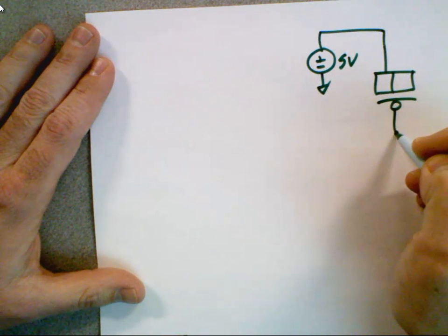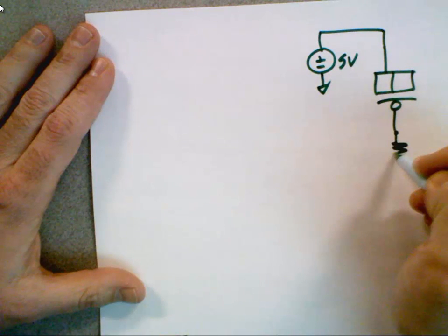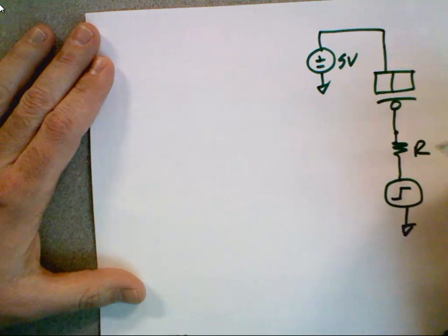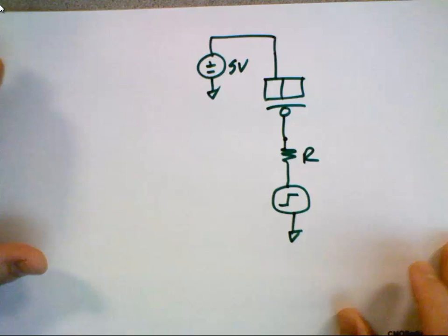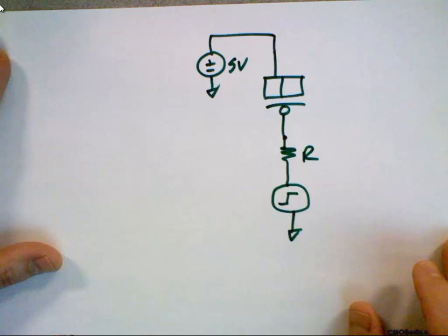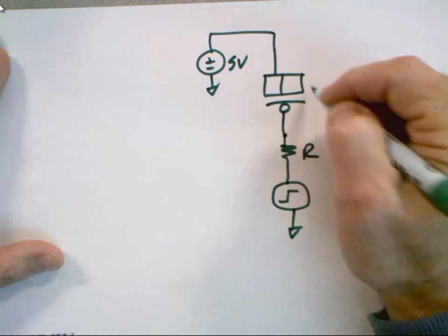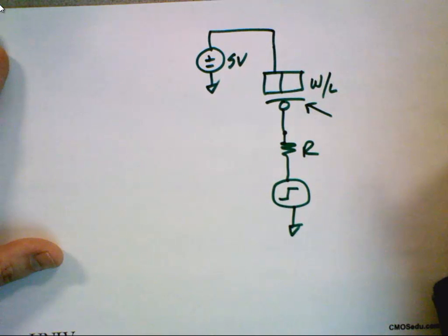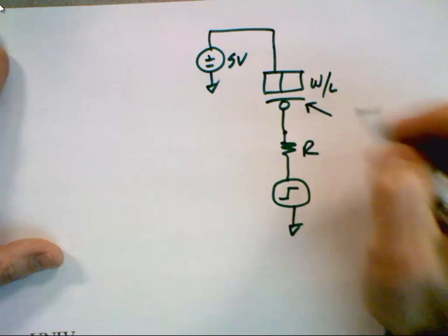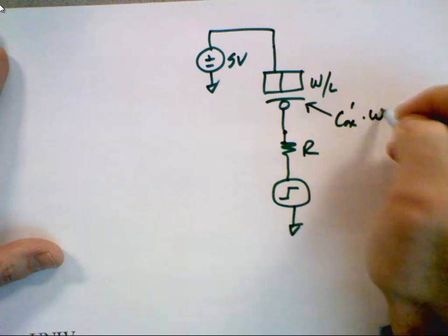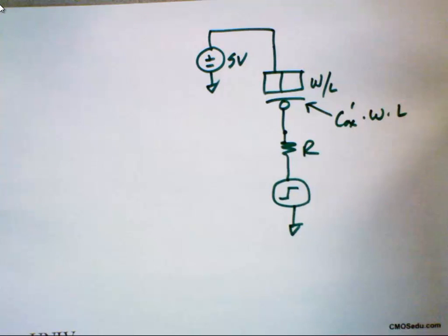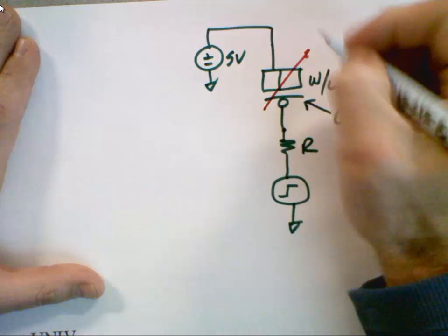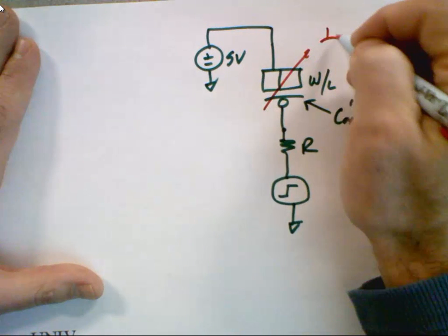And let's say, let's draw it crazy. And I ask you, simplify that circuit for me. First off, this has some W over L. What's the capacitance of this device? Okay, so in my mind, I'm thinking of this as nothing more, as long as it's in strong inversion, we're going to cover that again, as a capacitor.